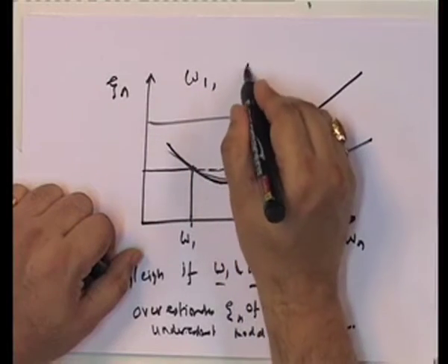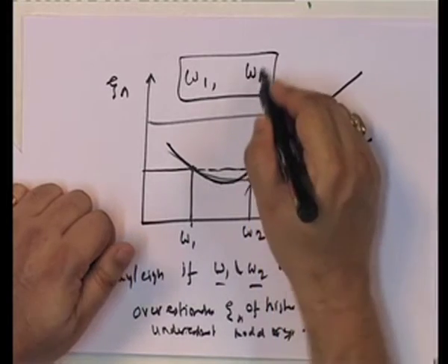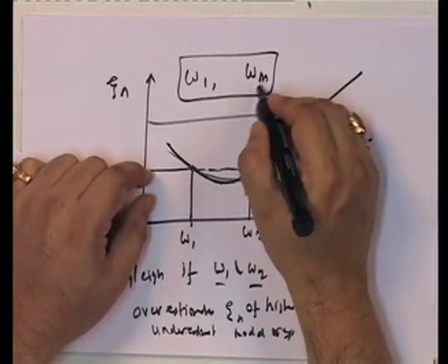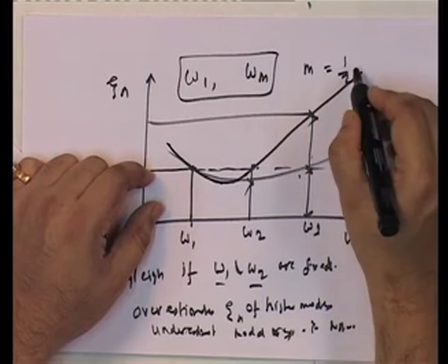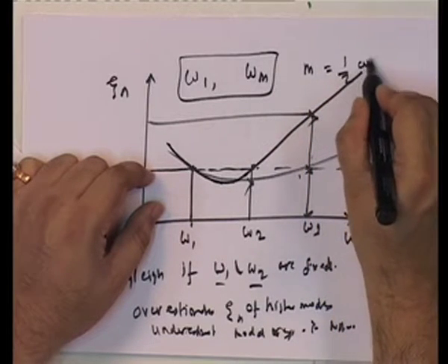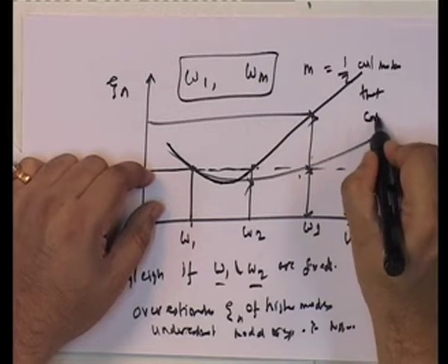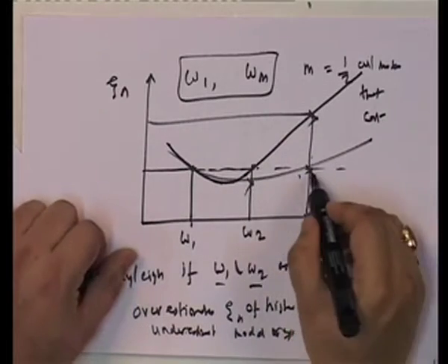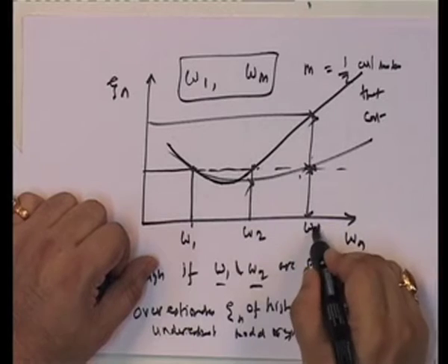The reason Rayleigh damping has been used is that instead of omega 1 and omega 2, you actually take omega 1 and omega m. Omega m is not really omega m, actually this m is approximately about half of all modes that contribute. Because then what happens is, let's say 4 modes contribute and I take omega 3.